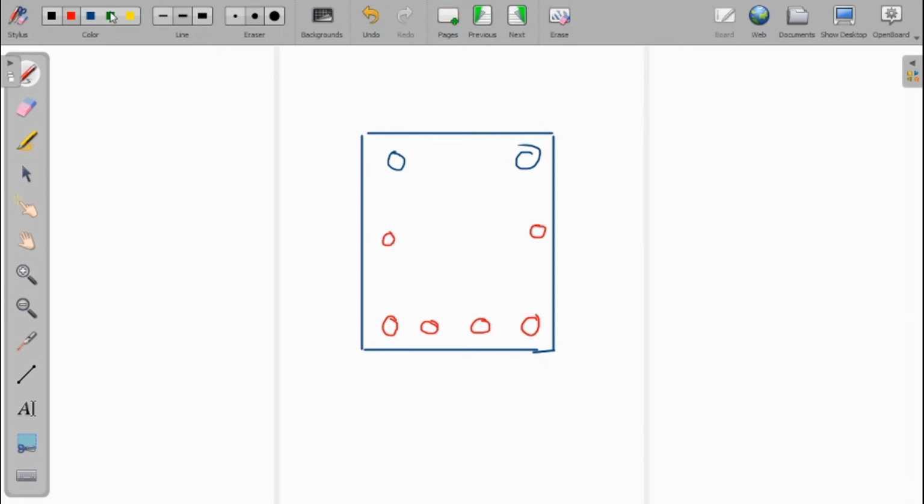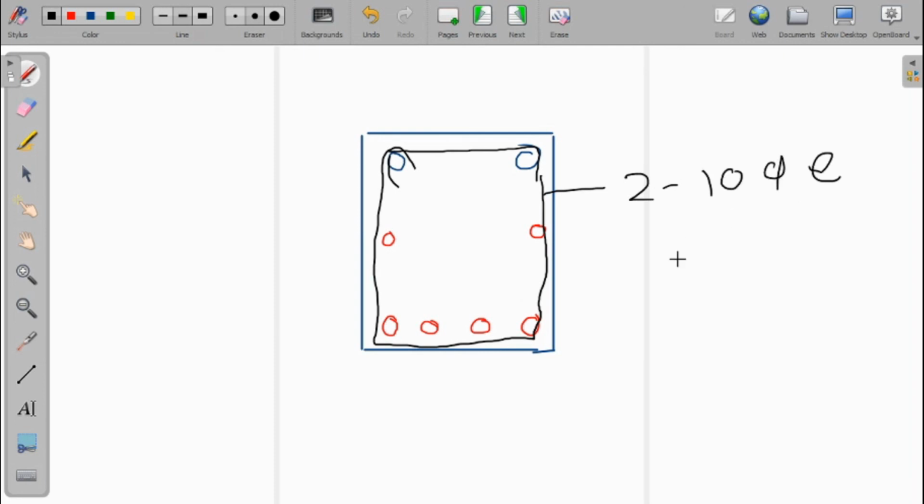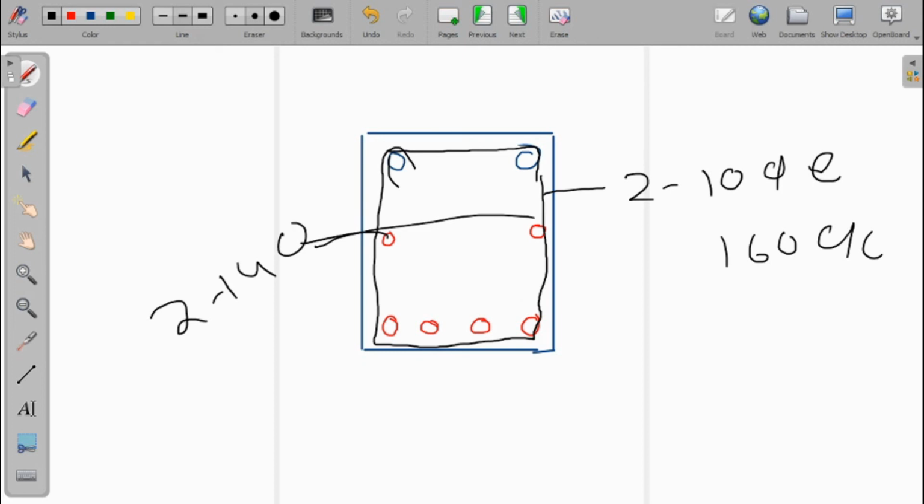Then what I did, I need to provide this shear reinforcement that I have calculated. Okay, so this was the shear reinforcement required. What was the shear reinforcement? 2-legged 10 dia at the rate of 160 center to center. The side face reinforcement was, what was that? 2 number of 14 dia on side face, okay, and this was 2 number of 25 dia plus 2 number of, what was that? 16 dia.